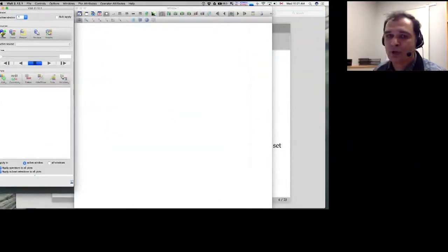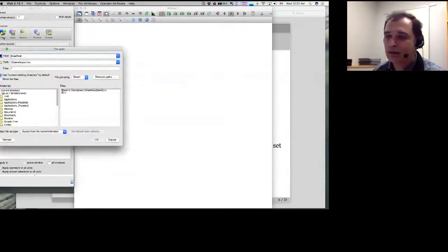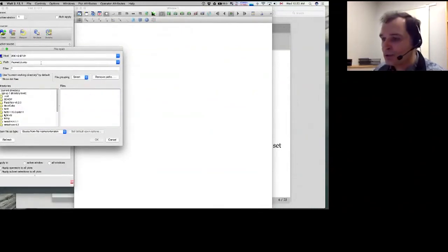All I have to do, I don't even have to start a VisIt service. The VisIt client on my laptop will do that automatically. I'll go to File, Open Dataset, and where it says Host, localhost, I simply navigate to Cloud West. And now I see the remote file system. Let me see, no, I don't have a shortcut, so I'll navigate to the same data directory. It's going to be data, ParaView Web, data, and I'll load the same file, decocube.vti.